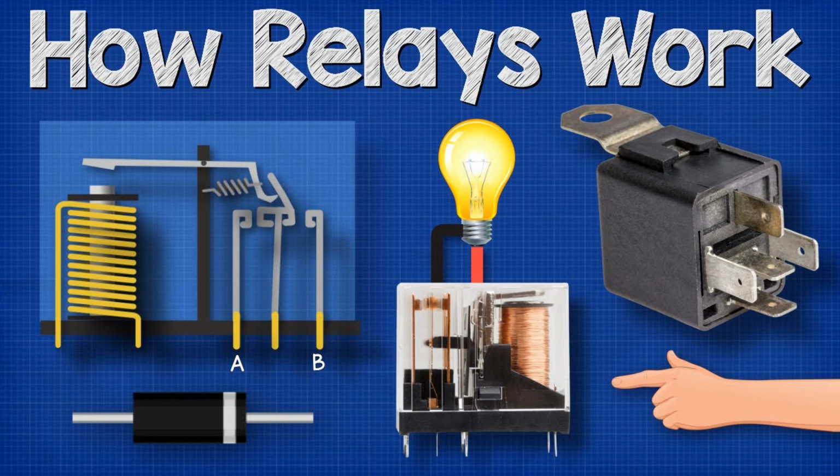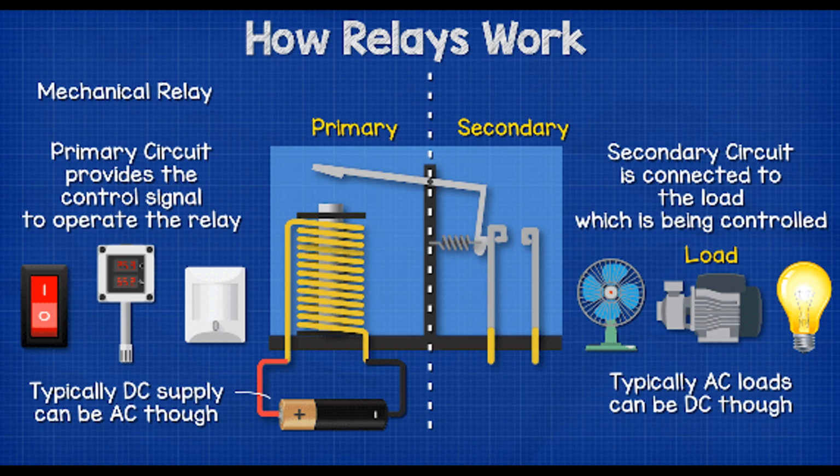Advantages: precision control. Allows for precise control in circuits requiring polarity-sensitive operations, especially useful in complex signaling systems. Energy efficiency. The assistance from the permanent magnet reduces the energy needed to operate the relay. Quick operation. With the additional magnetic field, polarized relays typically have fast switching times compared to standard relays.